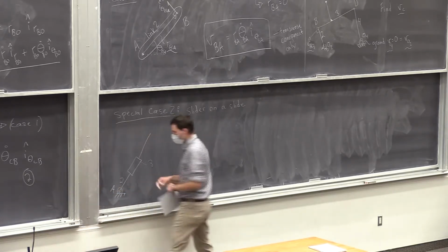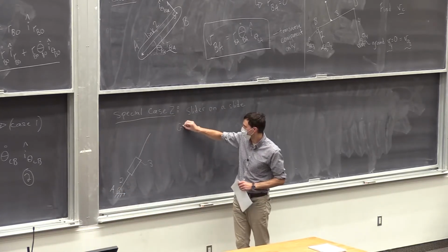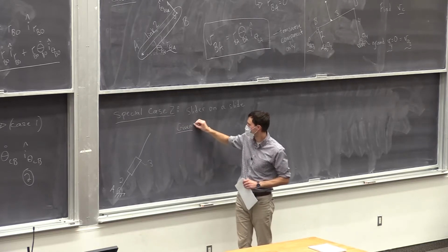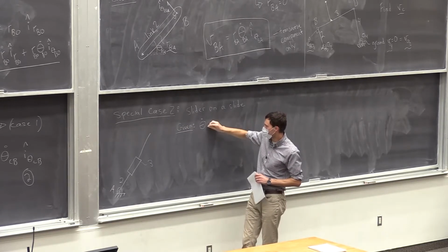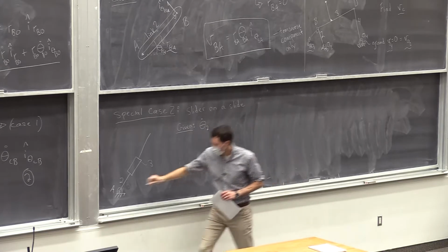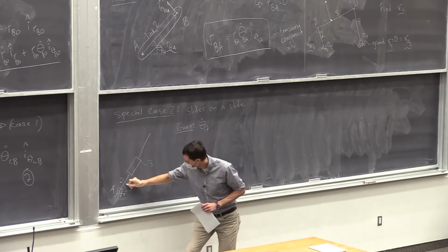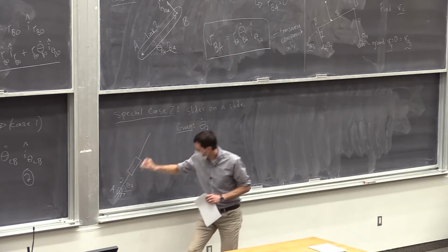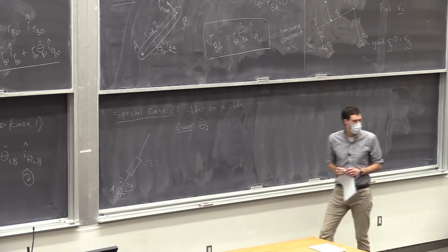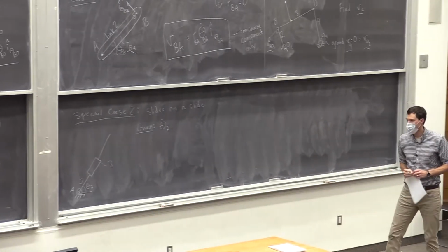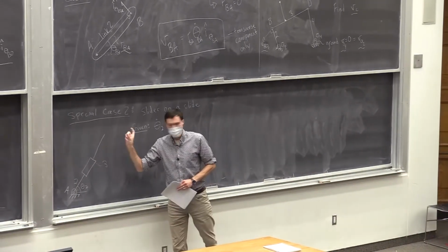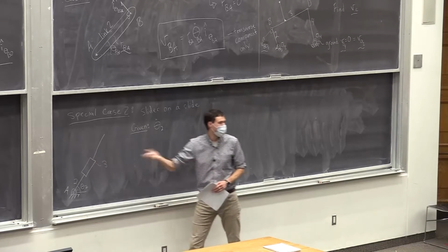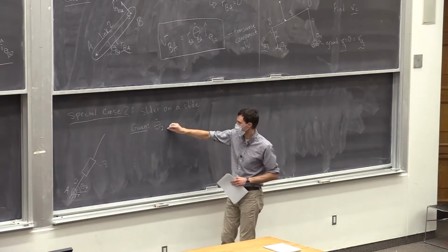Okay, and let's say we're given some info about this. Let's say we're given the rotation rate of that link 2, theta 2 dot. The angle of link 2 I'll define up from the horizontal like that. And link 3 is like a little collar that's sliding up and down on link 2.